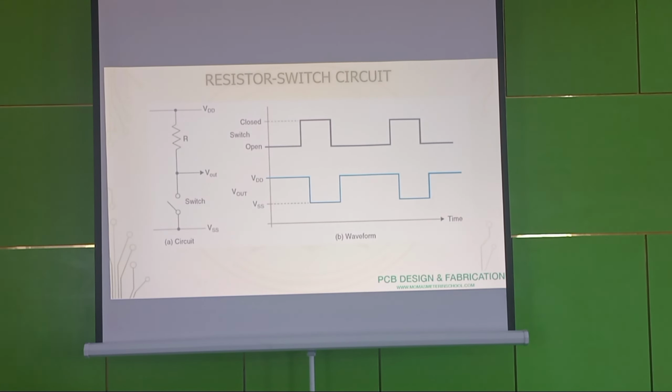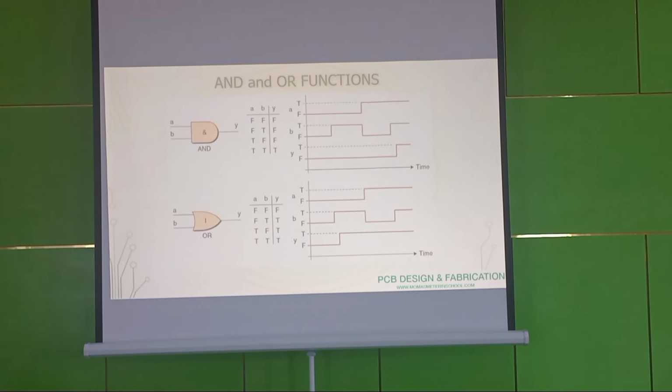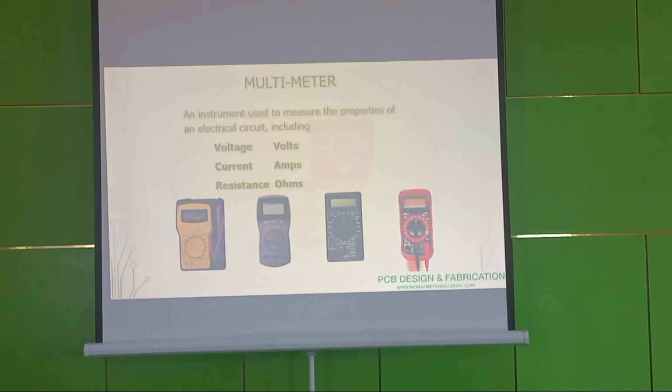So resistor circuits, logic gates, you should have knowledge about all these. Another thing is that you must know how to make use of a multimeter. It is very important. You must know how to use it to check voltage, current, frequency, or test your transistor, or do a continuity test, especially when you have your PCB design and you want to check what is wrong. You must know how to check all those things.